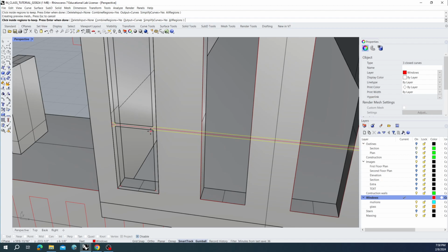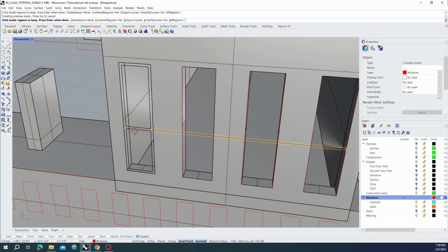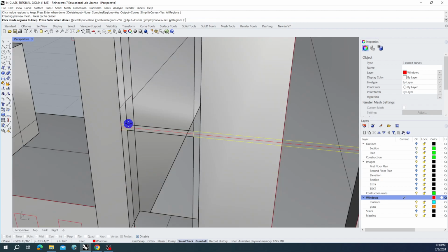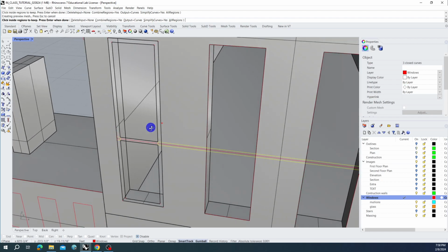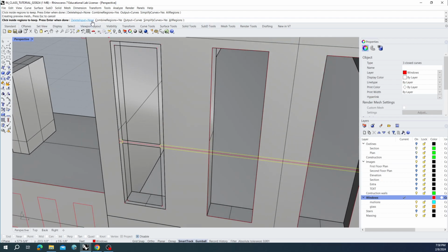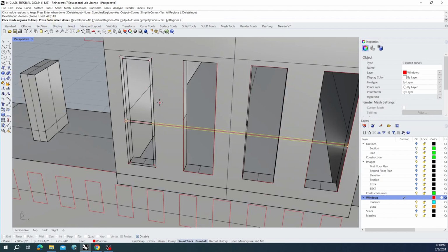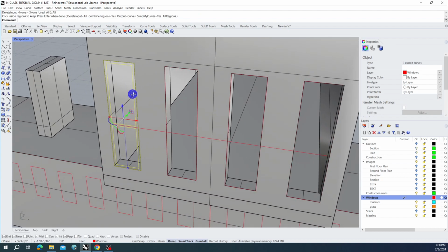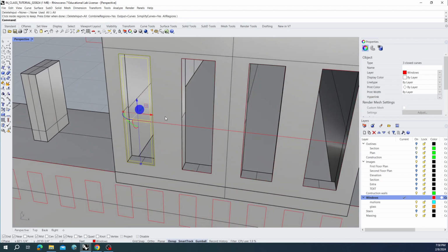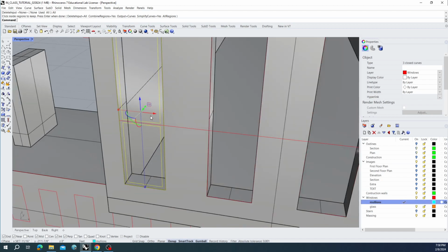So we were able to use curve boolean, and then decide which parts of the curves, which we're seeing bolded, the dark bold, we want to keep. I'm going to go ahead and delete all of those input curves. And we can see we're left with only these things here, which is the outline of our mullion.